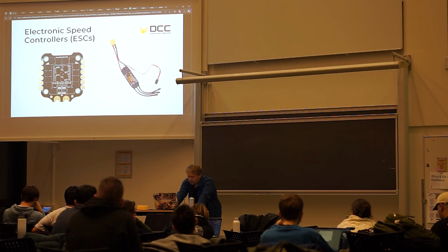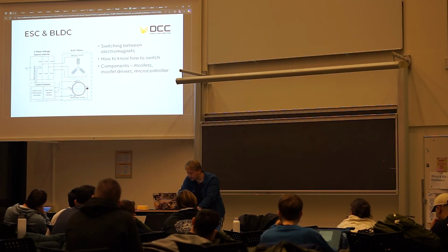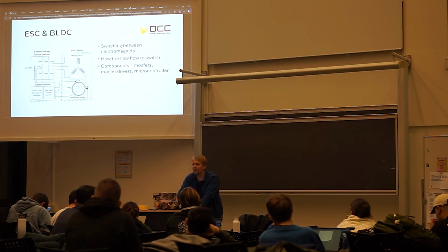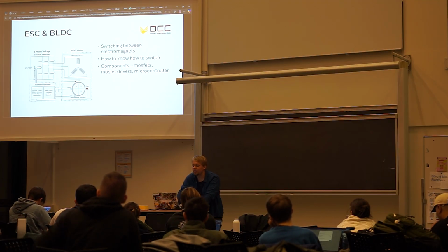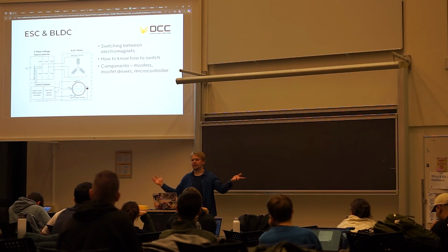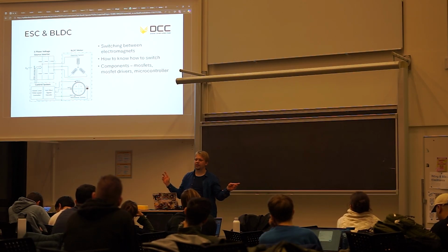So how does it kind of work? Well, this diagram has a bit different configuration. The point is the difference: you have sensored motors and unsensored motors. If you want to spin really slowly and accurately and still supply a lot of power, you quite often want to go with sensored motors.